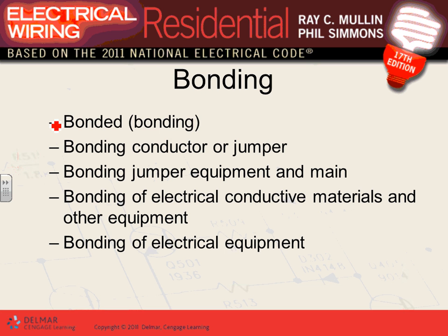There is a big sheet that I'll give you guys about grounding and bonding that you're going to like at one time. Okay, bonding. Bonding is tying two metallic objects together, guys, to put them at the same potential. That's what bonding is. Bonding and grounding also mean the same thing at one time. You could have a conduit, you bond the conduit, and the conduit acts as an equivalent ground conductor too.